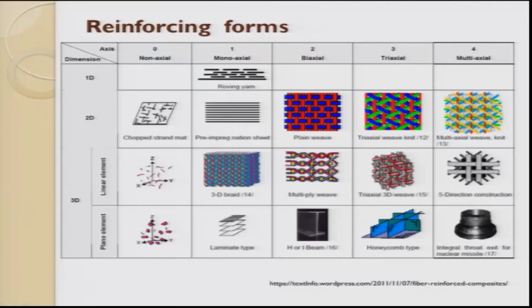So you can see here the mat is made in three directions. One direction is straight, the other direction is at 45 degrees plus, and the blue one, assume it is minus 45. You can have three directions weaving to make a 2D mat. Then let's move to the next. So this is multi-axial weaving. So what is the difference between triaxial and multi-axial? Why is it required? As you want to enhance your strength properties, you will always go for this.